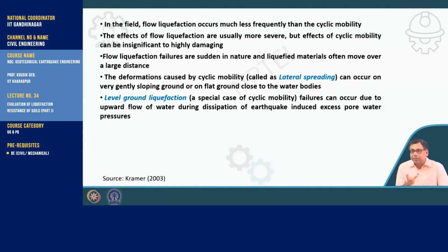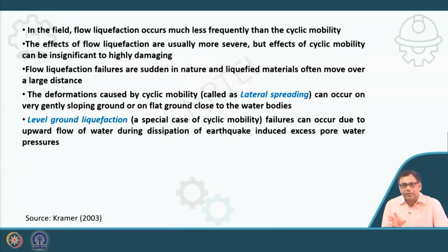If I say now I am concentrating only on cohesionless soil, so I will talk about the sand. First, unless I discuss the liquefaction susceptibility criteria for the fine grained soil, I will only talk about the sand. So that's why flow liquefaction can occur in loose sand, but as the shear strength in case of cyclic mobility is greater than the static shear stress of the soil, this cyclic mobility can occur for both loose as well as dense sand.